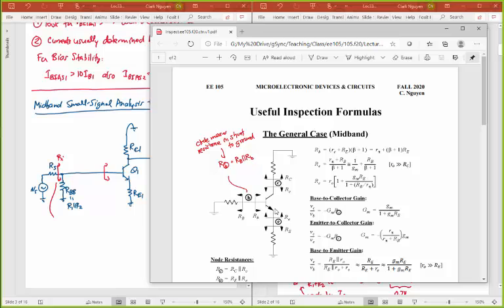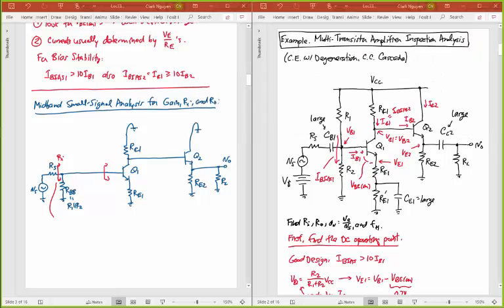We're really looking at this resistance R little b. We plugged in the hybrid pi model, and we derived what that is. If I have an R little b looking this way, this is the expression for R little b, either this one or this one. I'm going to write out this one, so it's going to be R pi plus beta plus 1 times whatever that resistor is right there. So right away, this resistance, I'm just going to write as R pi of transistor 1 plus beta plus 1. I can put beta sub 1 for transistor 1, and beta sub 2 for transistor 2, but I'm going to assume the transistors have the same beta here. But this is beta plus 1 times the emitter resistor RE1. And that's the resistance I see looking this way.